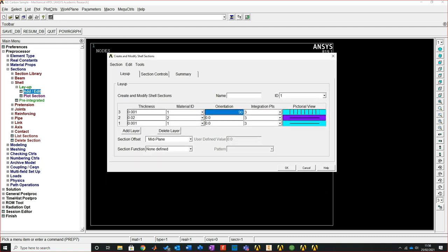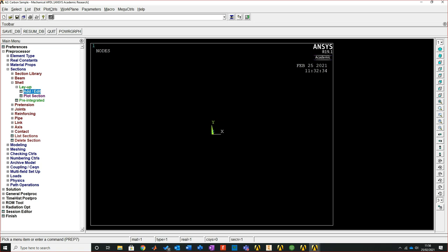Right, so I'm going to click OK. And now we have the meshing set up. We have the procedural process set up, because when we did all layers, we set up a layup procedure through our shells. So it now knows that whatever geometry I put onto it is going to be assigned with these meshing procedures that we've already defined. So it puts us in a good position.